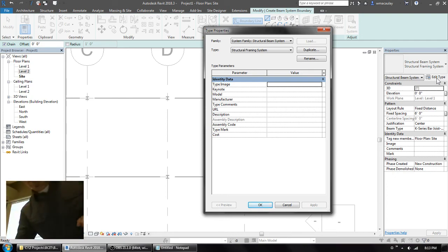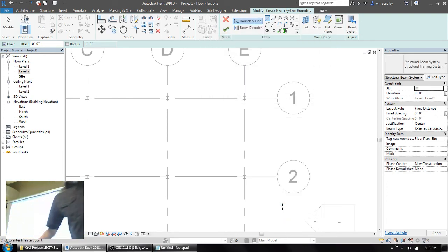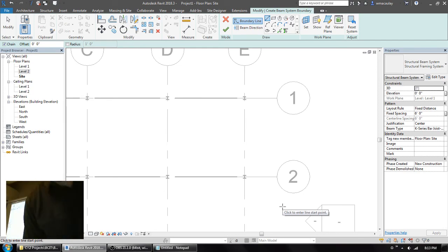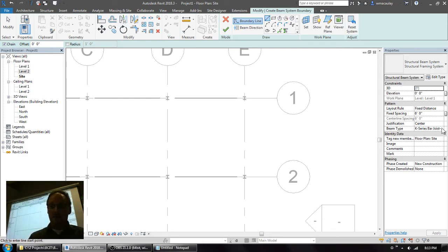So it means that whenever you do a beam system, it is going to be a one-off, but at least it is fast. So here's the process. First of all, you choose the structural member that you want to be used in the beam system. Beam systems are meant for creating a set of regularly spaced same member beams. So again, like a series of joists all in a row. So there is our open web steel joist, set a spacing of 7 feet.